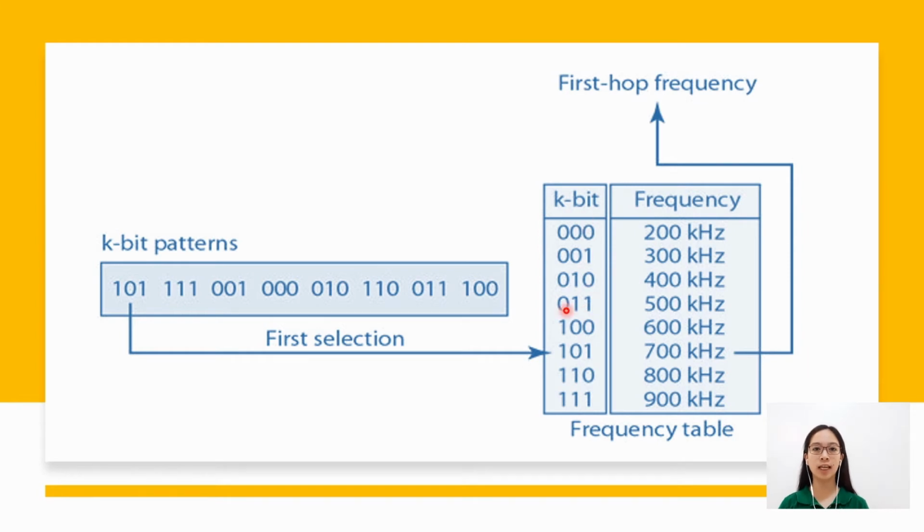At each successive interval, a new carrier frequency is selected. For example, 101 has a carrier frequency of 700 kHz. Therefore, this carrier frequency is modulated by the signal produced from the initial modulator to produce a new signal with the same shape but now centered on the selected carrier frequency. After 8 hoppings, the pattern repeats, starting from 101 again.